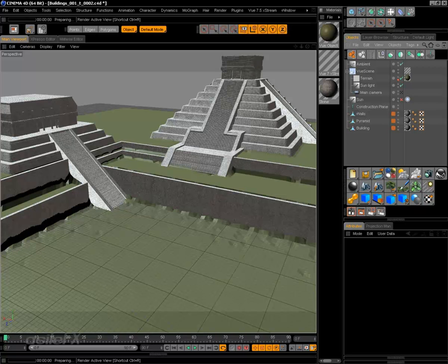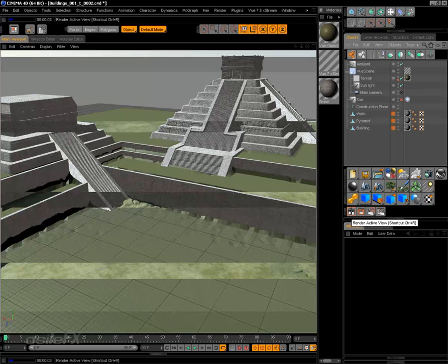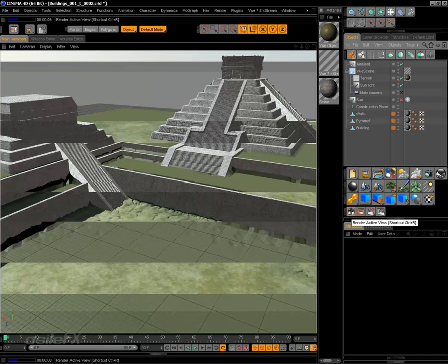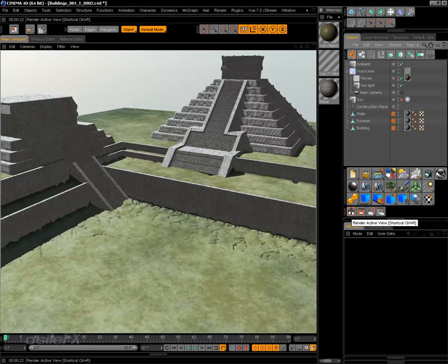But let's go ahead and just take a look at what we currently have and see how that's going to show up. And you can see the ambient light affecting the scene. If we're not to exclude the view scene, then it's also going to add that extra light to the view objects, which we don't want to happen. Now, unfortunately, this doesn't look very good at all. We'll definitely have to decrease that ambient amount, but for the most part, really, you're going to get the best effect from global illumination.